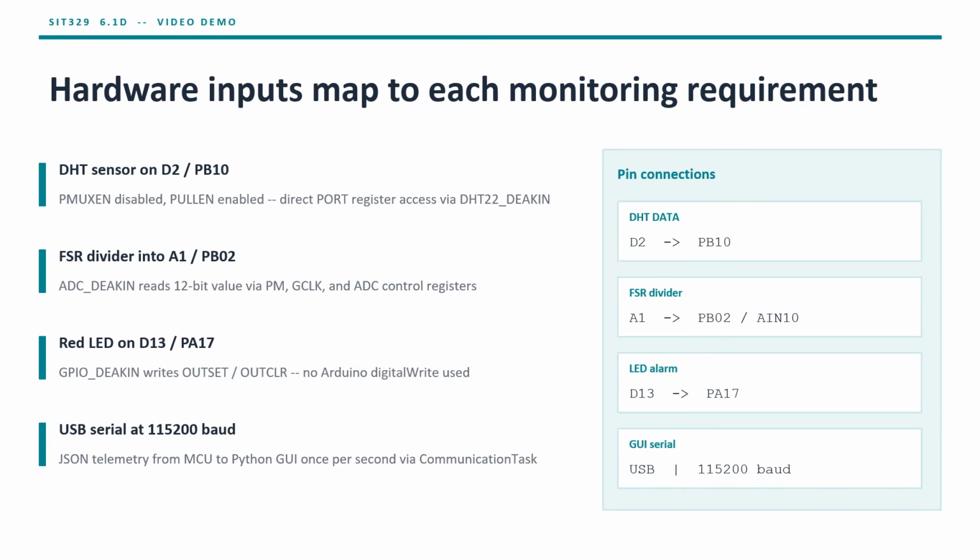The GPIO driver writes the OUTSET and OUTCLR registers directly to turn it on and off without any Arduino API calls. Finally, the USB port carries JSON telemetry between the MCU and the Python GUI running on the nurse computer.